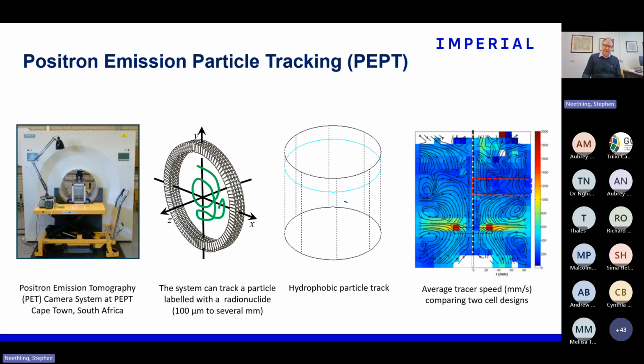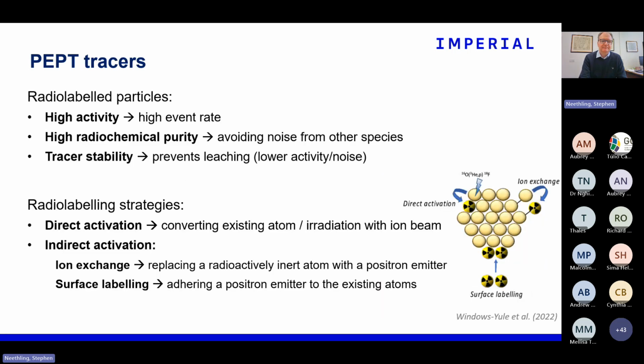But what you can do with those tracks is, if you do enough experiments, you can actually start to do appropriate averaging to get the flow behavior, flow loops, the velocities, etc., of your tracer as a function of position. And this becomes far more useful, as you can probably immediately gather, in terms of actually trying to compare with what is happening in a simulation of these cells.